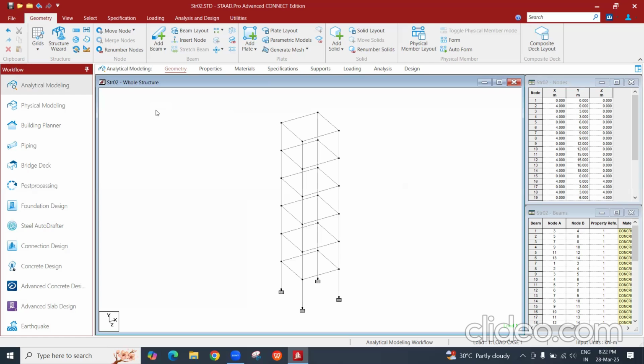Now the next one, we will go for response spectrum analysis as a continuation of this frequency. Then I can tell you the time history analysis and all. For response spectrum analysis, you should not put these frequencies. For that, you need to put the seismic definition. When you are putting the seismic definition, these frequencies are not needed. It will be automatically taken.